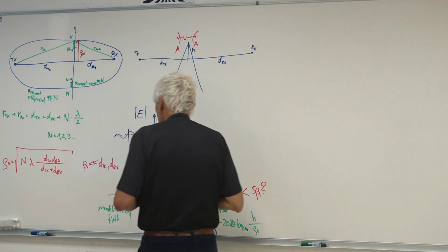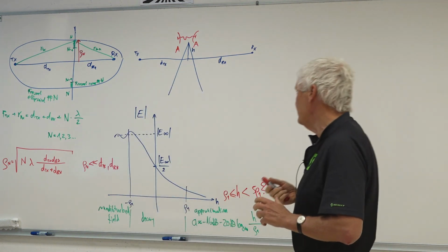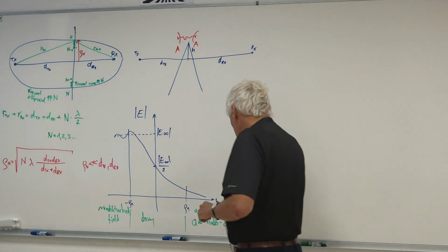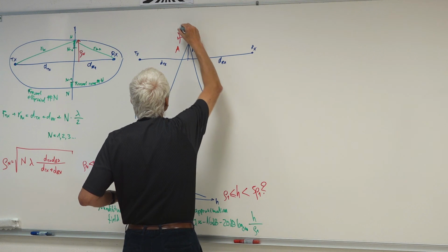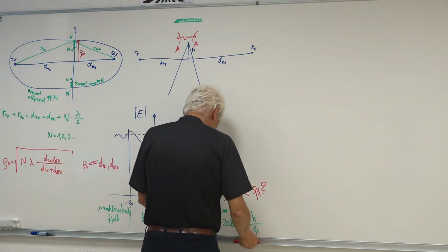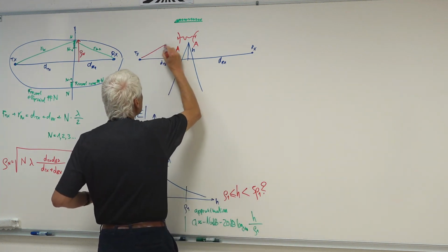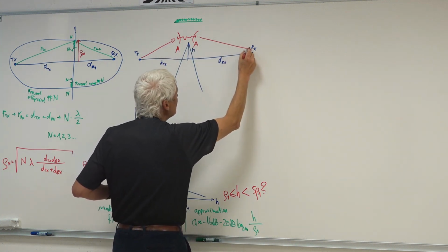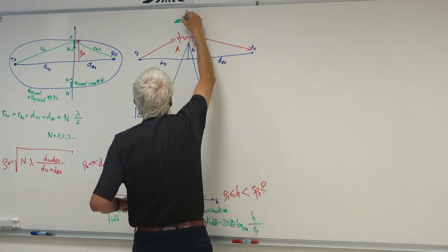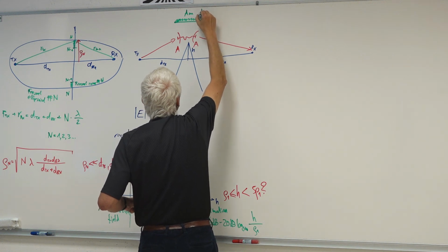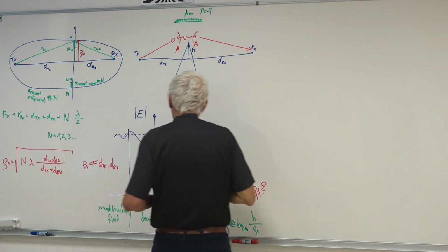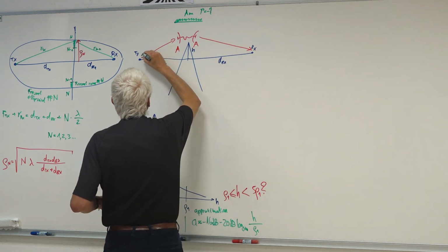Yes, but these two antennas have a certain surface, and we cannot make this very large, so here we have two radio links in series. That's difficult. What we could also do here is put a mirror. That may be more efficient than two antennas. A mirror with a surface may be equally efficient, because mirrors usually have a very good reflectivity. Gamma is equal to -1 for radio waves, not for optics. In optics, you have bad mirrors. And this thing could work.